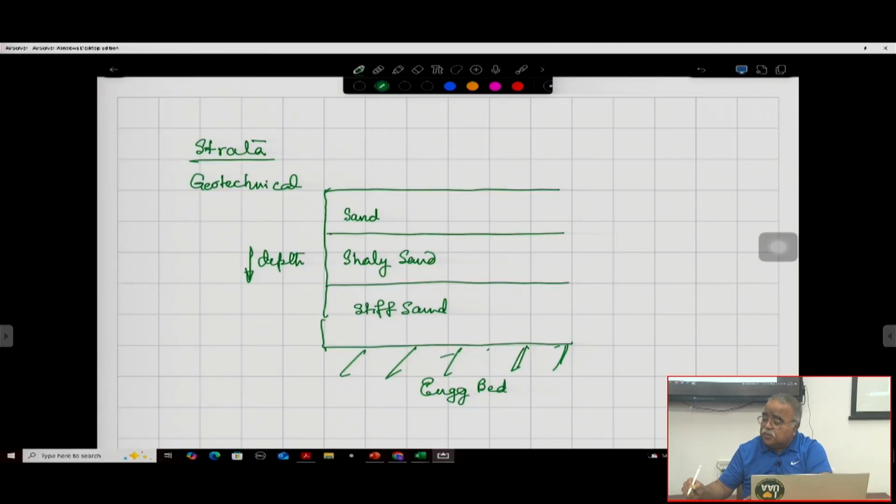Now this is at the site area. You generate the hazard-compatible time history for this area, and you put it onto the engineering bedrock, that horizontal time series, right? And the Strata program will calculate, assuming there is a surface, because everything has to be built on the surface. So these data sets will be propagated through by the Strata program.